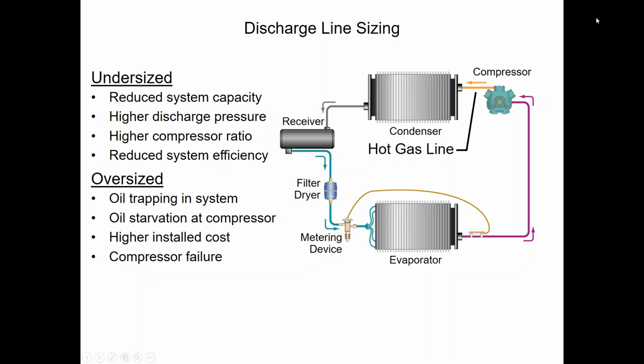Any time a refrigeration circuit is running, if you're doing comfort cooling or whatever, we're always carrying a little bit of oil with the refrigerant out of the compressor. So the oil is being entrained with the discharge gas into the condenser. That oil is traveling all through the liquid line, through your TXV. It's not a lot of oil, but it's a little bit of oil, through your evaporator, and then we're returning that oil back to the crankcase through the suction line. Well, as we return oil, we're also taking additional oil out through the discharge gas.